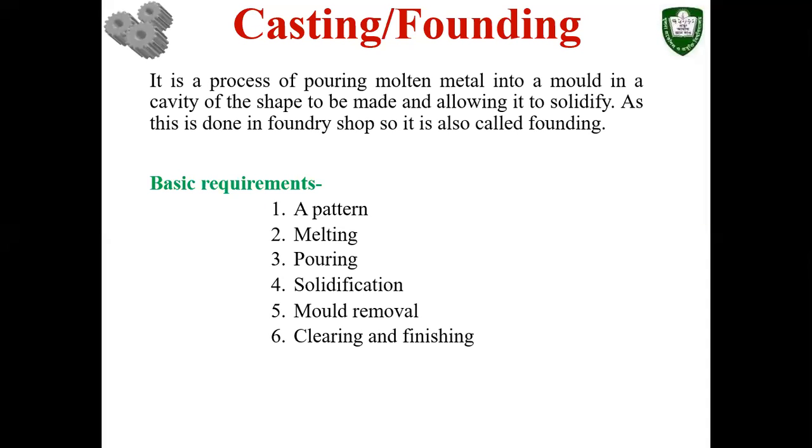That's also important, because you need to be really careful when you are pouring molten material into the cavity. Sometimes you don't have to, because it depends on what sort of casting you are doing. For example, if you want to do sand casting, then you need to be really careful during the pouring. You need to develop a pouring system.